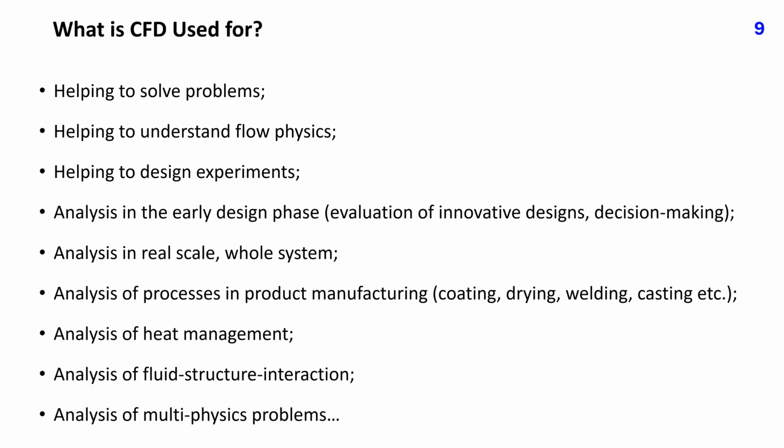A very important role of CFD is to help design experiments. It is always advisable to perform flow simulation prior to setting up an experiment. This helps to identify critical flow zones, the range of velocity, pressure or temperature variation, etc. In this way, one can select the most appropriate instruments and sensors, design measurement locations and strategy, data processing, and so on.